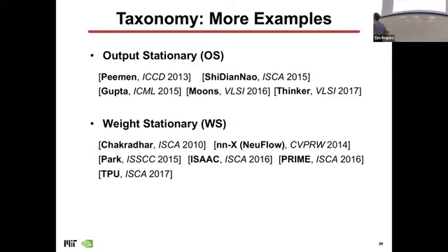So it's not just NVDLA, there are countless examples. This is a non-exhaustive set of accelerators that use some type of weight stationary configuration. TPU does this too. Okay, the tensor processing unit, this is the Google thing. They basically operate on weight stationary as well. So it's probably the most commercially successful way to map networks, because it's the simplest and the most intuitive, right? You map your weights, you map the brain to the processing elements, and then you flow the rest of the stuff through.